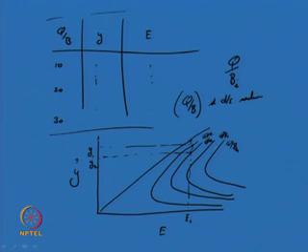Here you will see that the energy curve computed at section 1 1 is not intersecting this curve at any location. Therefore, the same specific energy is not available at section 2 2, that is what can be inferred. In such a case, for the given cross section q by b, the critical energy of the same curve will be taken as the specific energy at section 2 2.